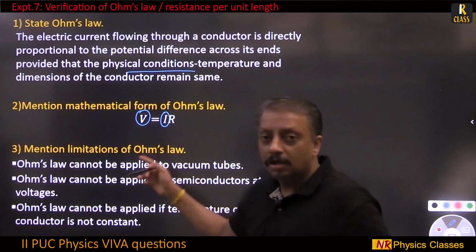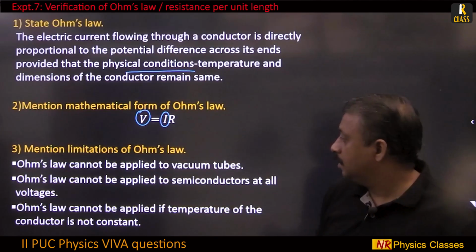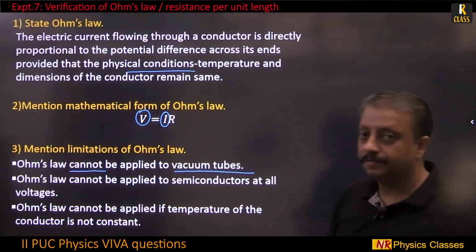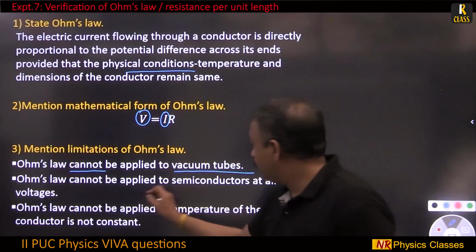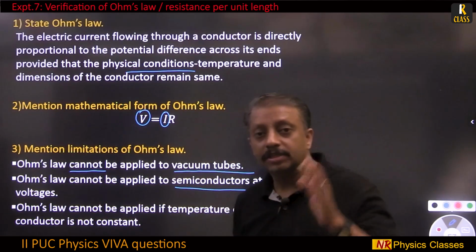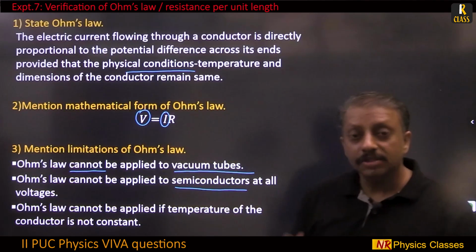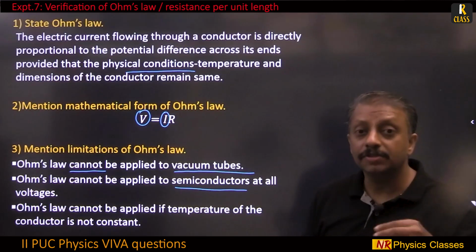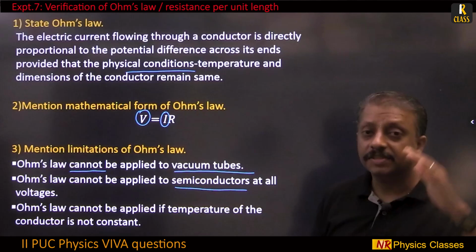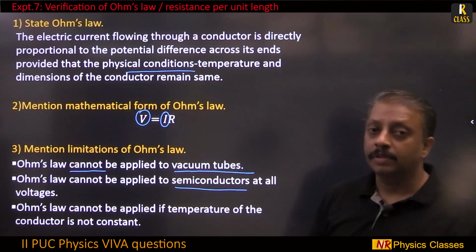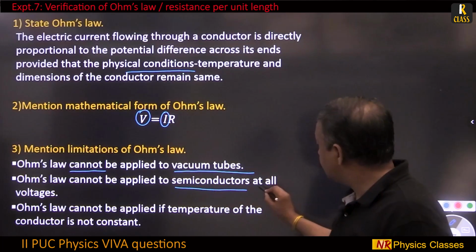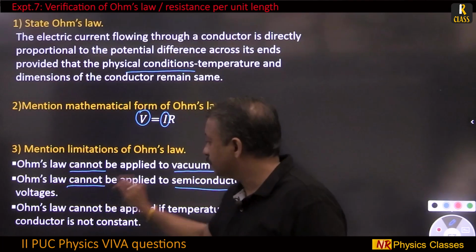Limitations of Ohm's law, also required for the board exam. It cannot be applied to vacuum tubes. It cannot be applied to semiconductors at all voltages. It's important to mention at all voltages, because in a semiconductor device we will be using Ohm's law only in a range, after some value or before some value, where linearity is observed.